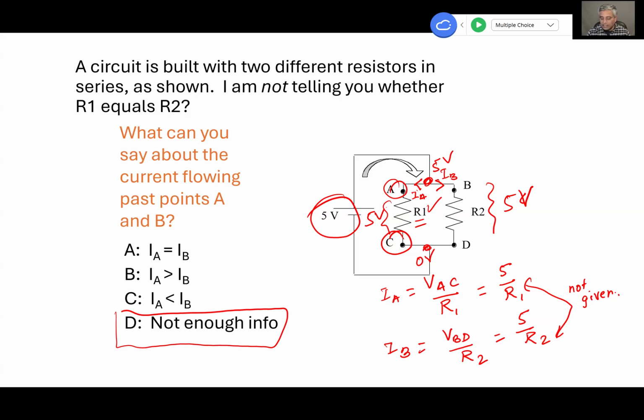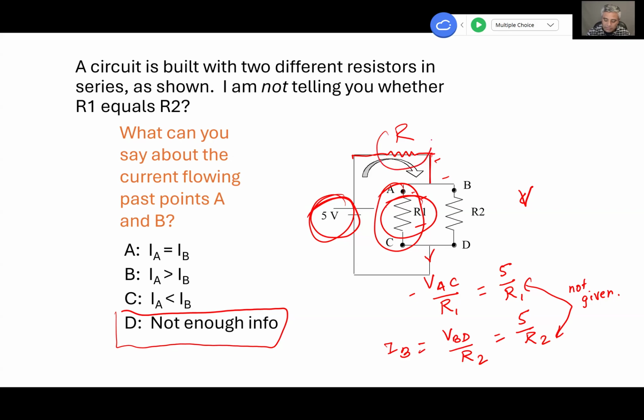So when it's in parallel, you can just divide voltage by that resistor, okay? If there are just these two, right? But sometimes you may be given something like this, for example. There was one in the weekly, we did one in the class, right? So we may have something like this. In that case, this voltage is not the same as this voltage over here, okay? Because part of it drops there. So be careful on that.